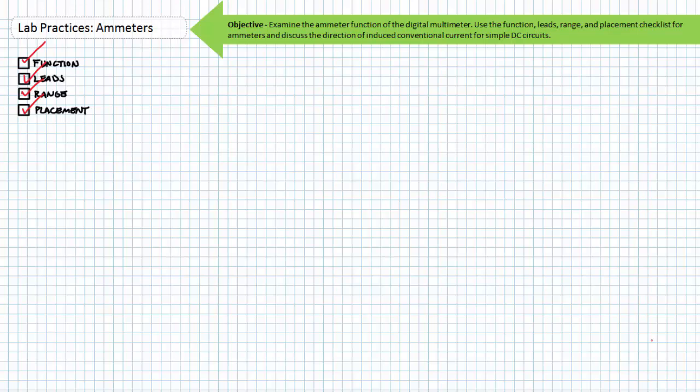If the lab group in front of you accidentally shorted the ammeter and blew the fuse, the ammeter won't function regardless of its correct placement. The blown fuse is now an open in your circuit. Without a complete path, no current will flow, nor will any voltage drop be observed across the resistor, even if the power supply is on.